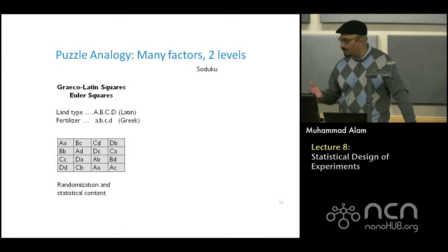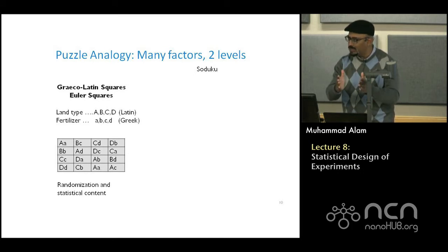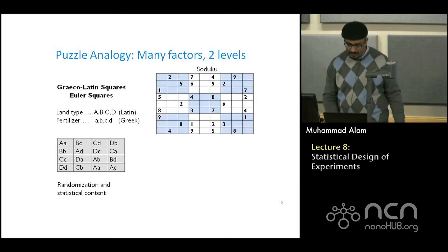For example, the 400 wafers I talked about in Intel, if you do one set of experiments based on only one set of machines, now maybe the operator of that machine has not adjusted it properly. So the results that are coming out have a bias simply because you ran a set of experiments with this. But if you randomized it completely, then the machine to machine variation would have averaged out when you are doing the final result.